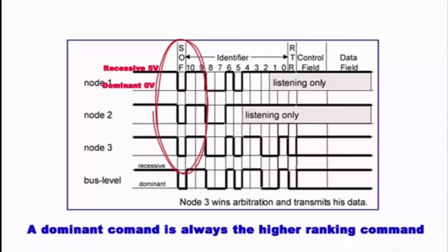Folks, I have read that a certain protocol works opposite of what I've just explained, where 5 volts is a dominant and 0 is a recessive. I will not worry too much, as this is not the norm, and I somehow do not think we will see this in the types of cars we work on, but I felt I should throw it out there for you.